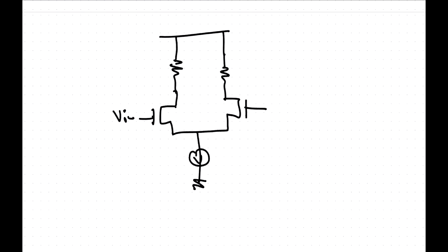So Vin plus, Vin minus, Vout minus, Vout plus. Okay, so this one here you don't need common mode feedback, because the common mode is defined by these resistors. They fix it. The trouble is that very often when you make gain structures, you have two current mirrors. To have high gain, you need a very high impedance, so you use active loads. So you have a current source and a current sink meeting in a node. And if there's a slight difference in the output impedance, you don't know where it sits. Whereas this one here, you do.